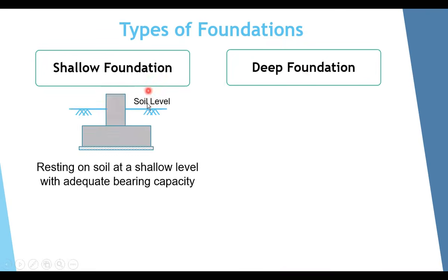For shallow foundations, you can see that the footing or the foundation will be resting on the soil at shallow level. If this is the soil level, it will be close to the soil level, and we use this when we have soil with good bearing capacity.